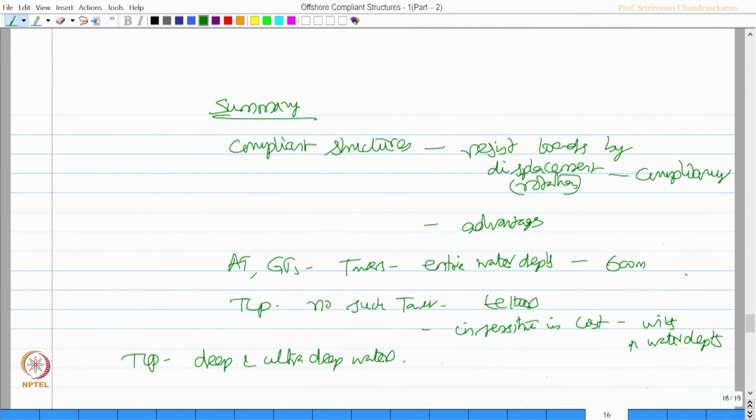So, T0 horizontal component will resist the load, whereas vertical component will add weight which improves its stability. So, the TLPs have good recentering capability, restoration concept, simple in design, insensitive in cost with respect to water depth, and simple installation. So, this is what we call as TLP mechanics.